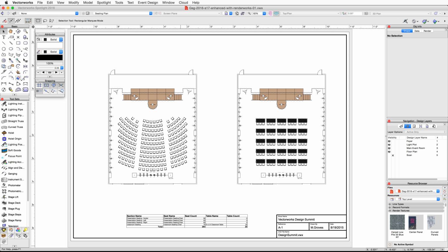In this video, we're going to add some additional textures and then create a few rendered views from Renderworks Cameras. First, we need to create a ceiling for our rooms. We're going to duplicate the existing floor slabs to create a ceiling for both the ballroom and the foyer.